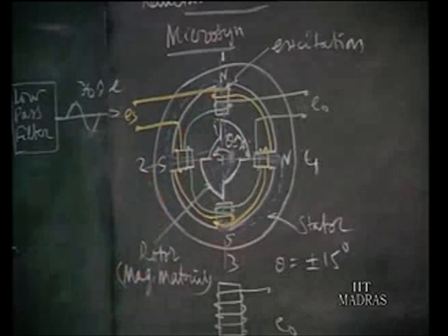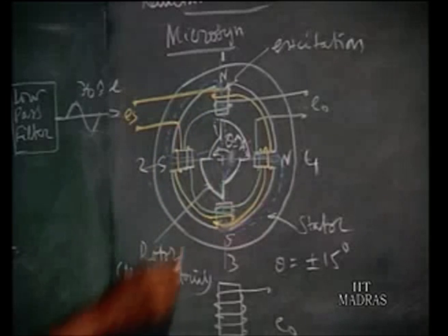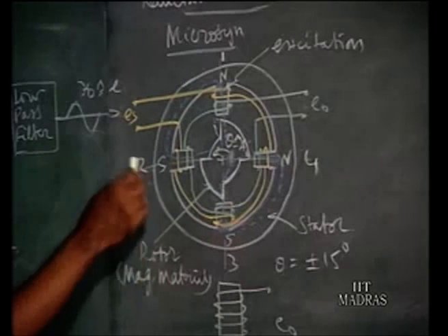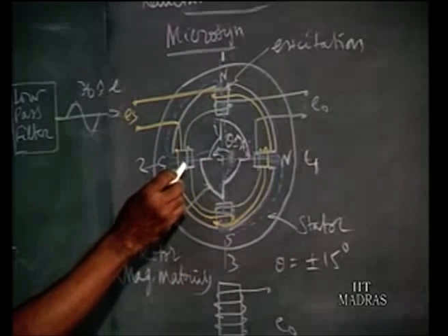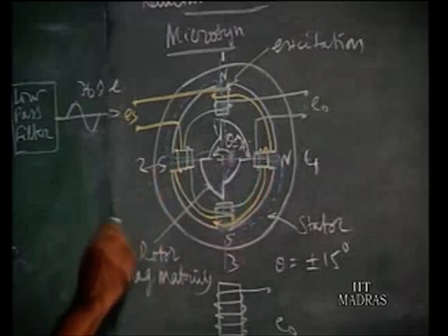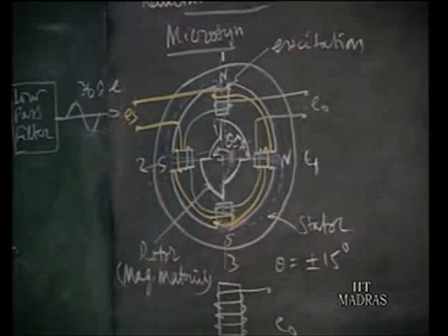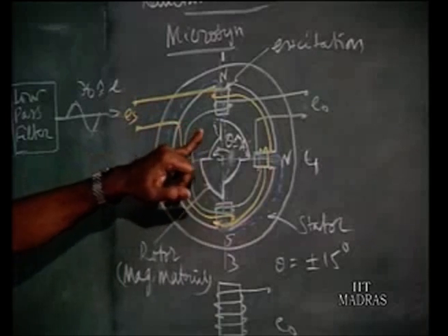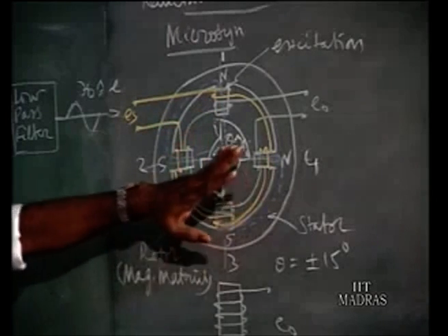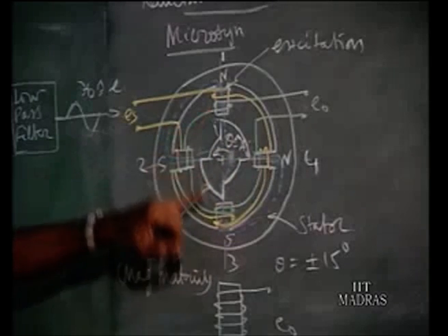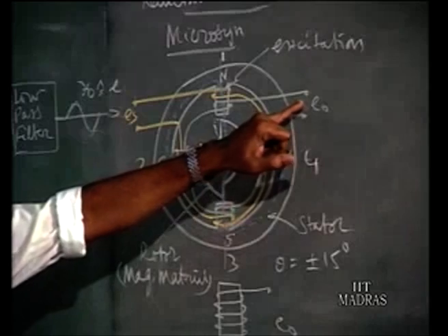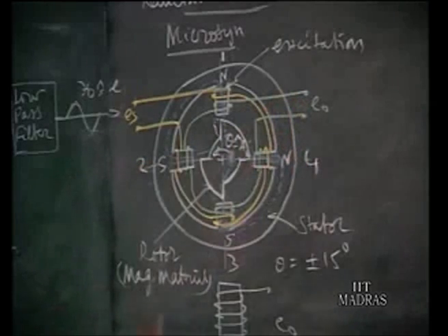That is similar to our secondary coil. So one coil is made up of the windings 1 and 3. The second secondary coil will be made up of 2 and 4, and the voltages developed in these secondary coils will oppose each other. So when they are all connected in series, you will find two adding, two subtracting, and the net voltage appears here.